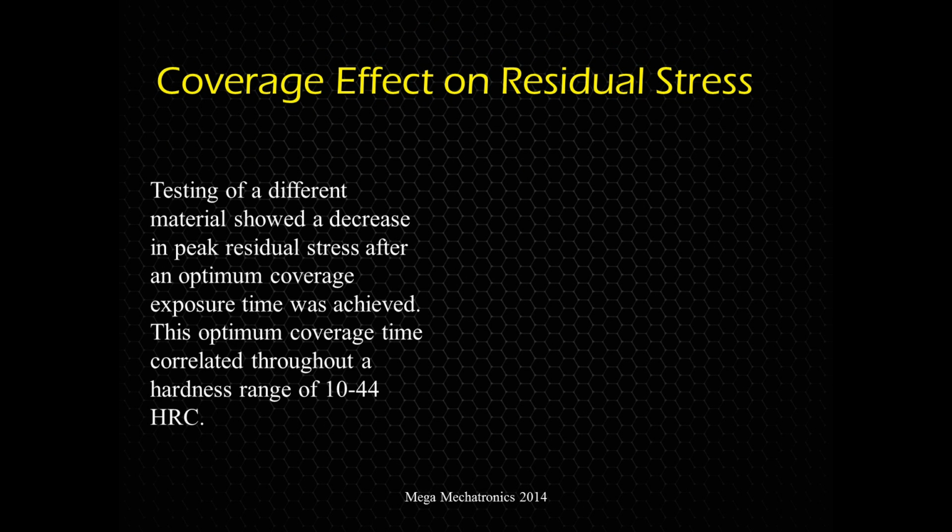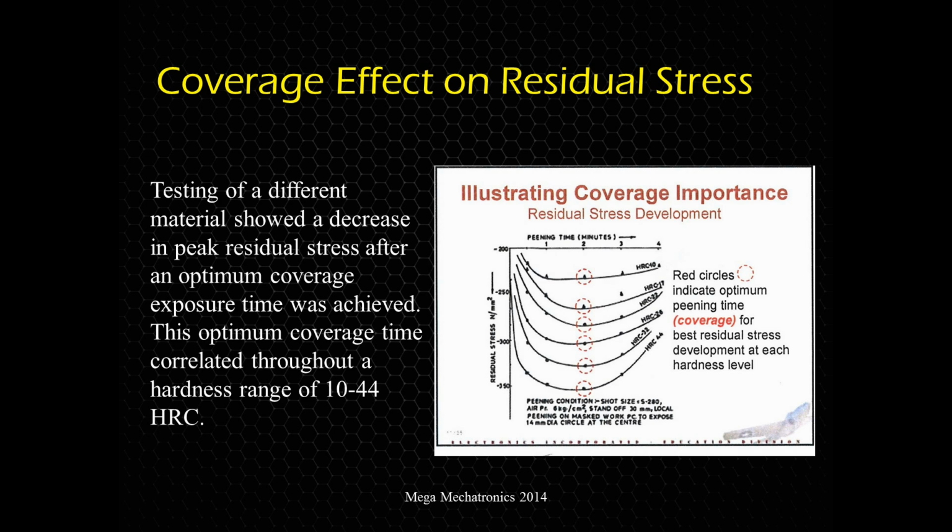But on a different material, you can imagine, hopefully you're not using this material, it actually shows a reduction of residual stress, which is going to be related to your fatigue strength. So the more residual stress, the likely better fatigue life you are going to achieve. So those are interrelated.